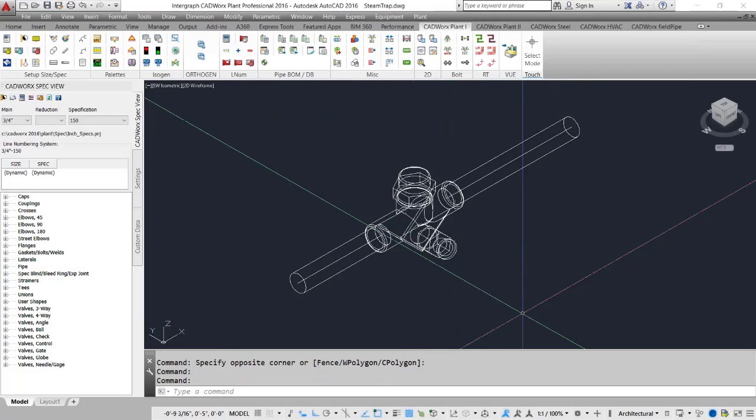I can also create a custom S key under the valve category and then even transfer that S key to the specialty item subgroup for my bill of material. But how they are dimensioned on the ISO is completely dictated by the S key and your style settings. So if my style settings are set up so that all of my small bore valves are dimensioned to the center of that valve, or they are dimensioned to the ends of the valves, then that is how the component would be dimensioned on the ISO.